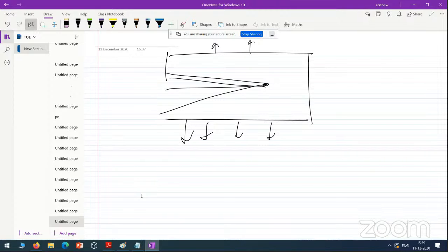The direct contribution from sigma z will be zero, but because of the Poisson's effect, you have a contribution from sigma x and sigma y that will generate some strain in the z direction. A similar argument can be applied to the plane strain problem as well. In plane strain, the strains are confined in a plane, but you can have stress in the other direction, right?